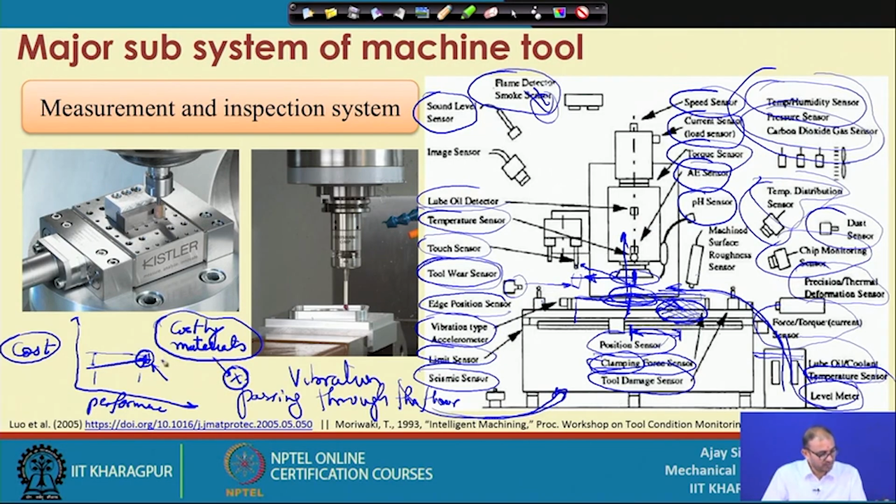So, you have to add some more sensors here, right. Now the cost will actually follow an exponential curve. You are adding some more sensors so that you can monitor the costly component machining, but still you are getting a reasonable amount of performance. If you see this, your performance and cost are almost the same. For the same 10% increase in performance, you are getting a 10 or more percent increase in the cost of the machine.